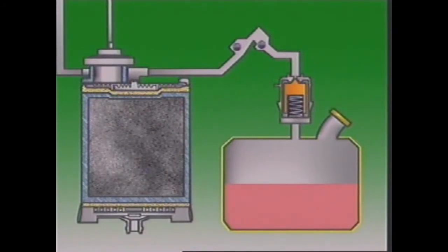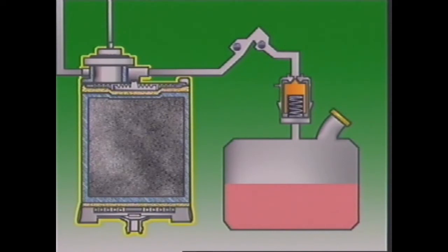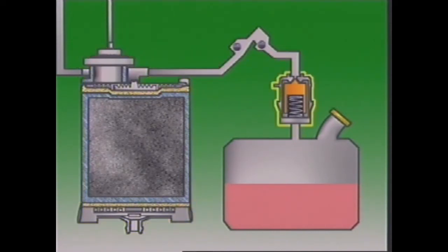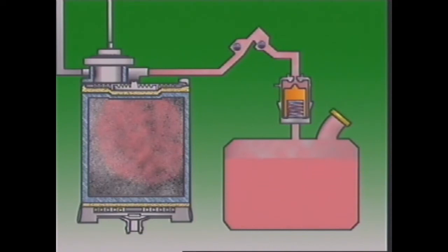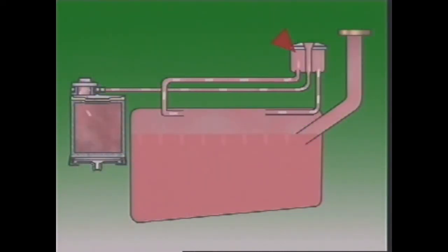Vapor from the fuel tank is trapped in a charcoal canister and stored there until it is burned in the engine. A vapor or vent line with a check valve connects the space above the liquid fuel with the canister. This valve opens when pressure starts to rise and lets vapor through, but not liquid. Liquid fuel closes the check valve and blocks the line, stopping liquid fuel reaching the charcoal. Some systems have a small container called a liquid vapor separator above the fuel tank. It also prevents liquid fuel reaching the charcoal.